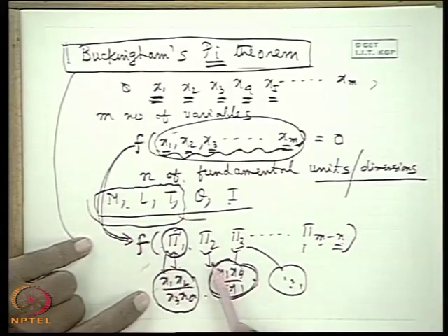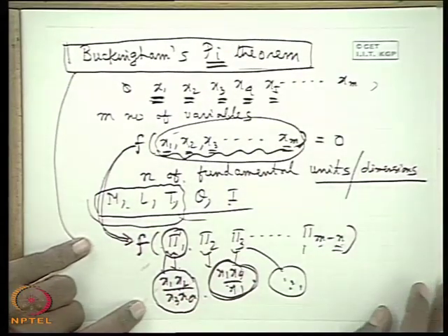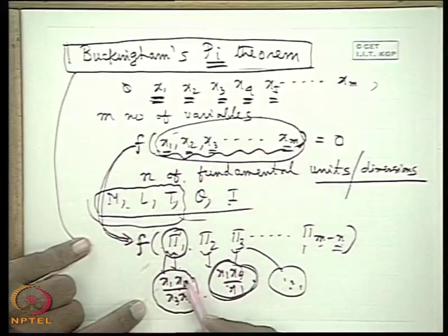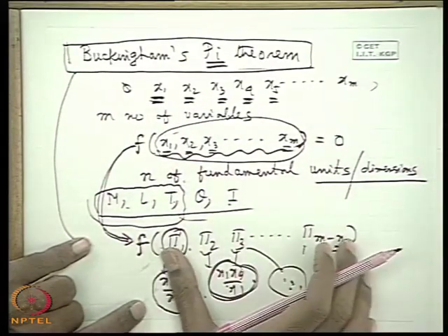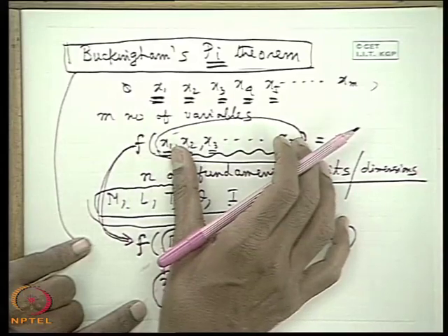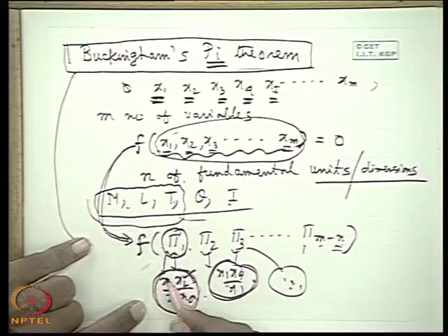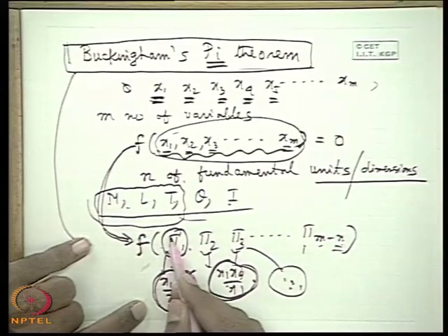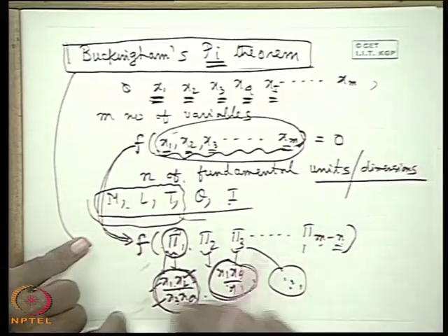the same problem, and we have already seen the beauty of it through the pipe flow problem. Just an example I have given, that if we reduce the number of variables from dimensional form to non-dimensional form, that means we can vary one of the variables to vary the non-dimensional terms, any non-dimensional term, so that the effect of other variables defining the non-dimensional terms are clear or can be implemented.